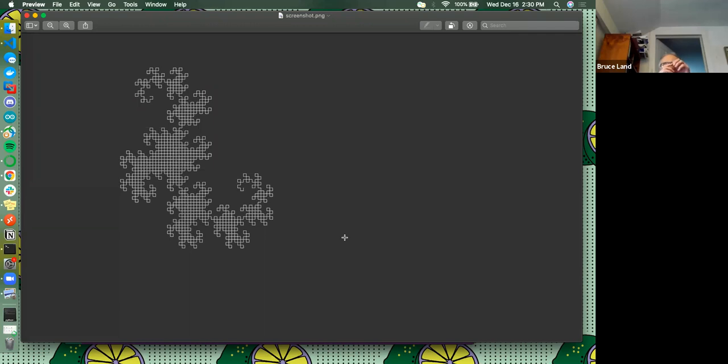But still, it's only milliseconds, right? It seemed to take a lot longer when we were having the issue of graphing off the side of the screen. But in addition to the fact that we're clearing the M10Ks every time, there's going to be a point where the string is too long to graph within the bounds of the existing screen. And since we do have that negative quadrant issue, it wouldn't really scale out well. So every factor of 2 in the number of M10K blocks buys you about 1 iteration. To get to 20 iterations, you would have used up all the M10K blocks by far.